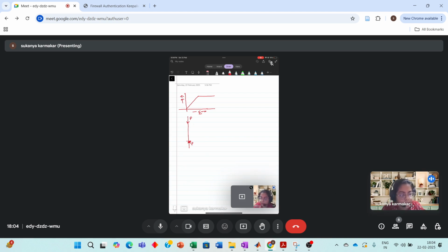Let's assume this is the free body diagram for this column. But what will happen if I write down the equilibrium equation in a deformed configuration? The column will buckle slightly. Suppose I perturbed it, pushed it slightly, so that I study its stability.